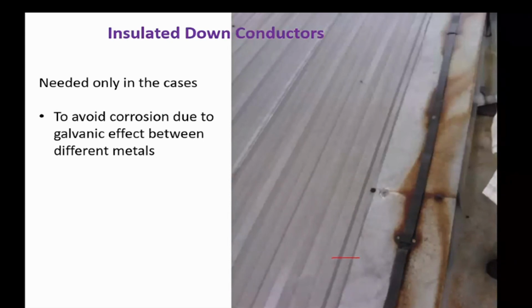Okay, but be careful if you're having your down conductors or air terminations on a roof or wall material which is also metal.